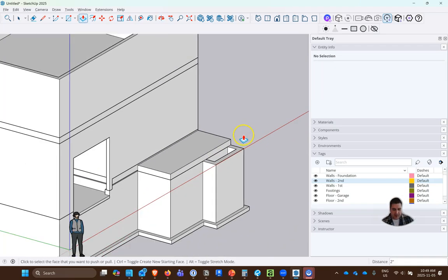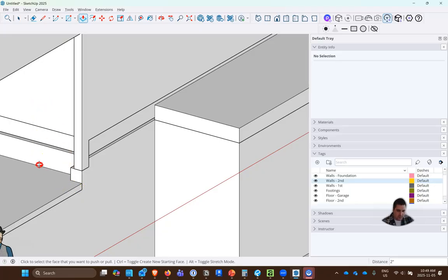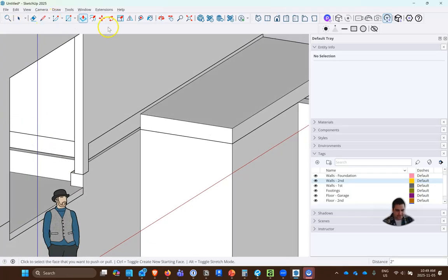And then we may have a couple steps down. If you were to measure from this, because we obviously are amazing at stairs now since we did stairs a few weeks ago, we're 2'1". So I would say we're probably 4 steps to grade. So yeah, 2'1", 4 steps, basically 6 inches per step. Often on the exterior, a lot of people will keep steps to a little bit of a smaller number, not necessarily go up to 7, but we can play with that number.